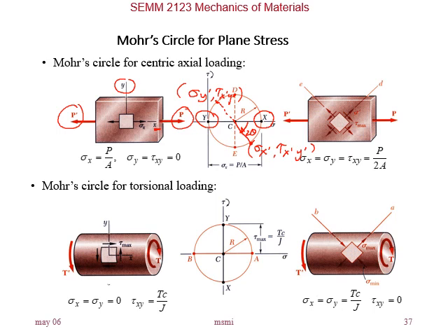So the direction of the shear stress on this right hand face depends on the external loading applied. If the external loading is going in this direction here, if you imagine on this side is going upwards, right? At the back there, it seems to be going downwards. So here on the right is going upwards, and upwards is positive tau. On the left is going downwards.